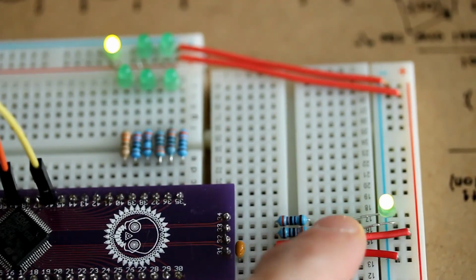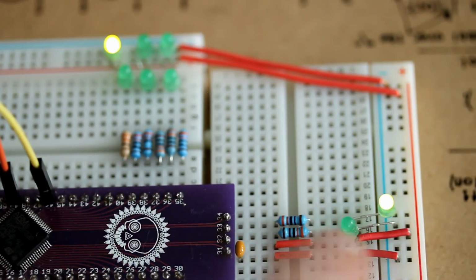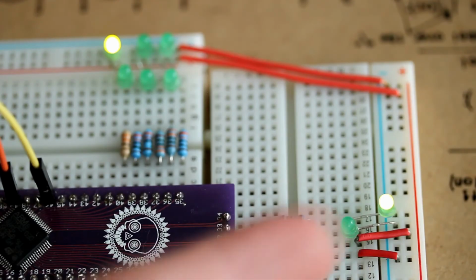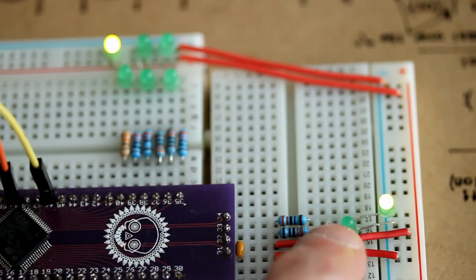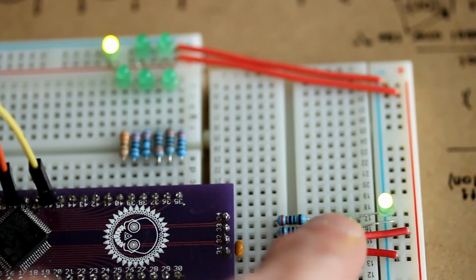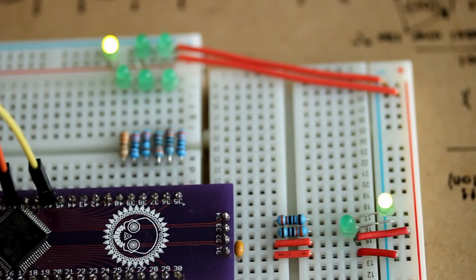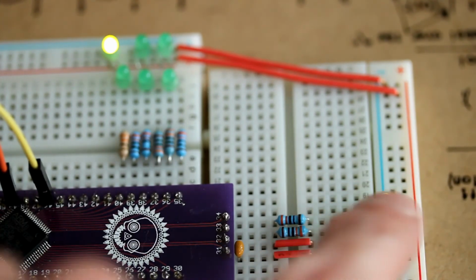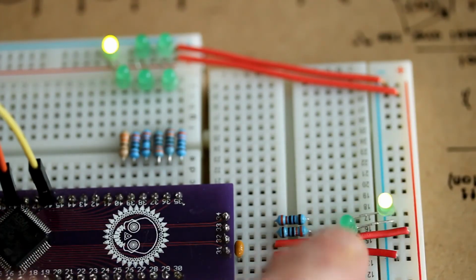You can see that these two pins changed because the lowest bits, the first 2 bits in a change from a B to an A, is only going to change from this being a 1 to this being a 1, because that would be 2. This would be 1, and then putting a 1 in this position would be a 2. A 3 would be both of these lit up. So a C should cause both of these LEDs to light up.